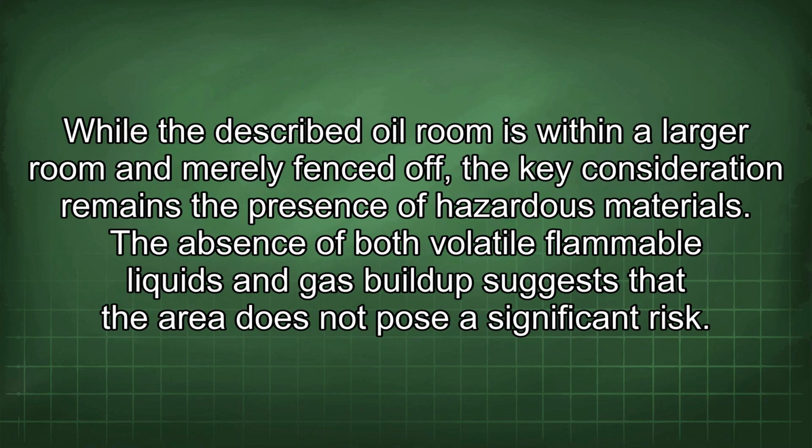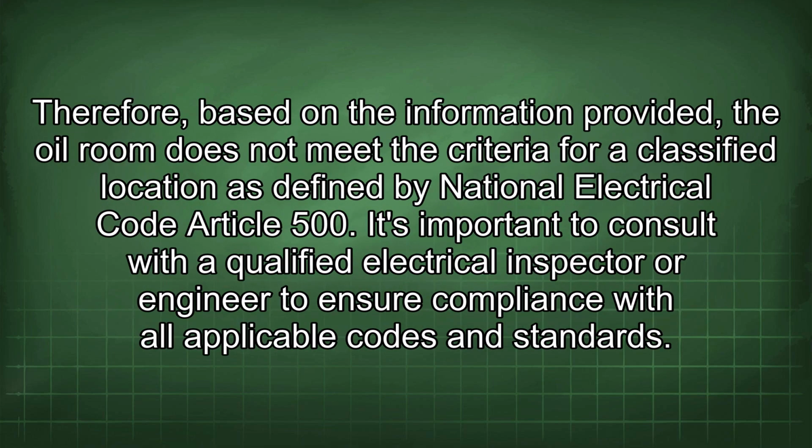While the described oil room is within a larger room and merely fenced off, the key consideration remains the presence of hazardous materials. The absence of both volatile flammable liquids and gas buildup suggests that the area does not pose a significant risk. Therefore, based on the information provided, the oil room does not meet the criteria for a classified location as defined by National Electrical Code Article 500.